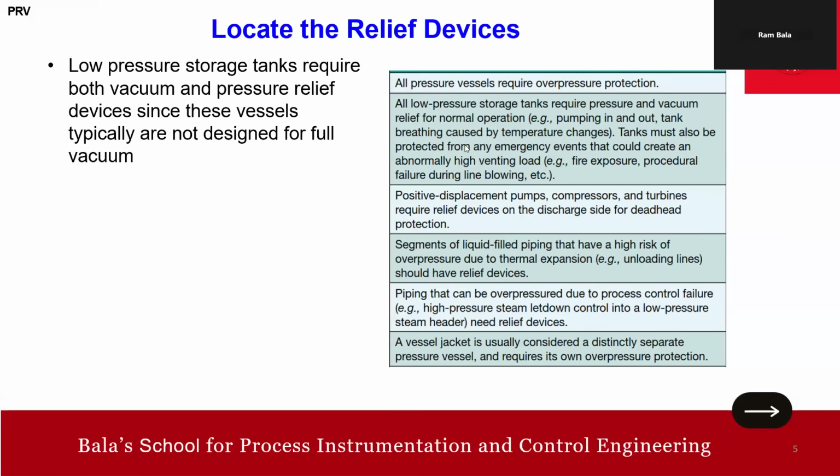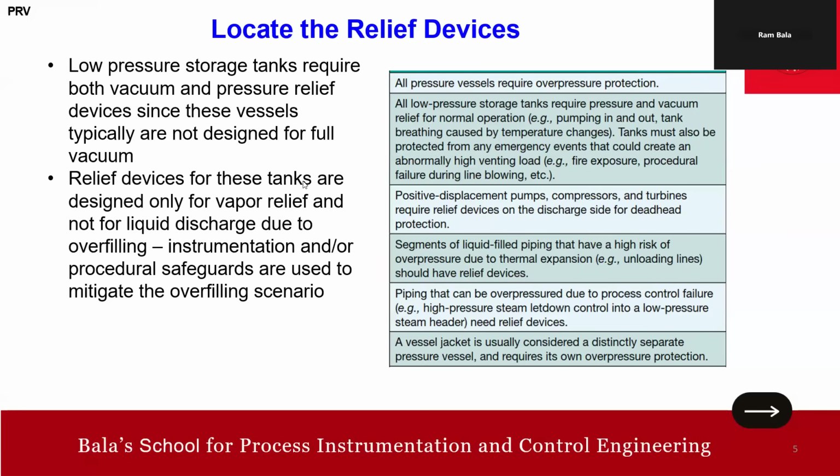Okay, now we talked about this, right? Low pressure tanks. Low pressure storage tanks require both vacuum and pressure relief devices, since these vessels are not designed for full vacuum. The relief devices for these tanks are designed only for vapor relief, and not for the liquid discharge due to overfilling. Just remember, friends, relief devices for these tanks are designed only for vapor relief, not for the liquid